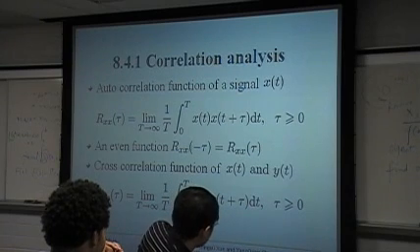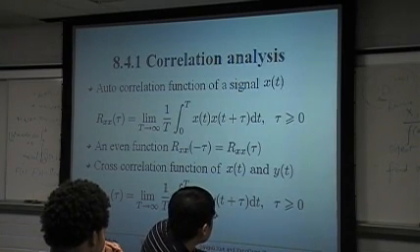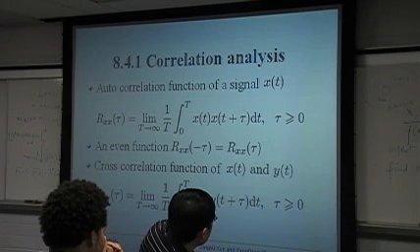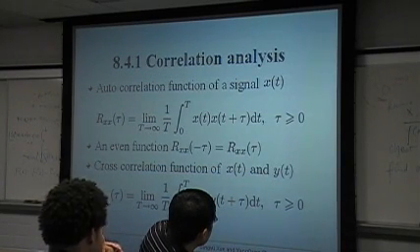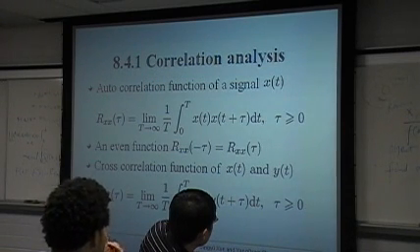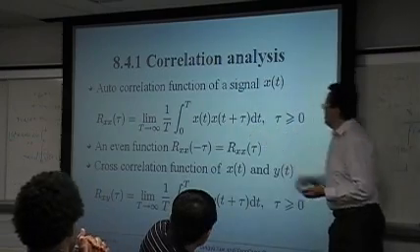We can substitute the variable t in the original x function by t plus tau. We can call it x1, x of t plus tau. This is the Matlab command that we can use. So if we declare x, then we can easily find this term by using substitution.